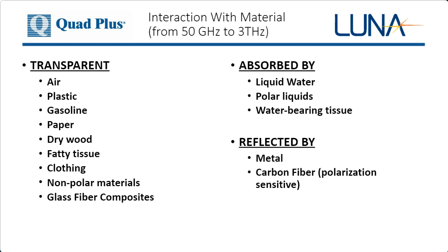A little bit is okay, but too much will just absorb, as water is a polar liquid. And for that reason, we really can't look much into the body because we're mostly water. It's reflected strongly by metal. So of course, that's going to figure into the measurement of these pipe coatings. And carbon fiber is also conductive in one direction, and so you can't get through that either.